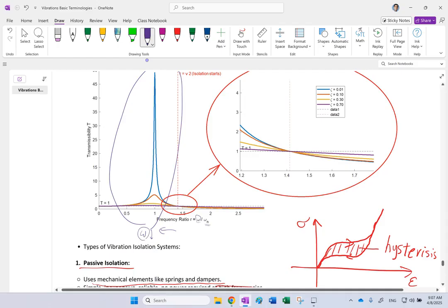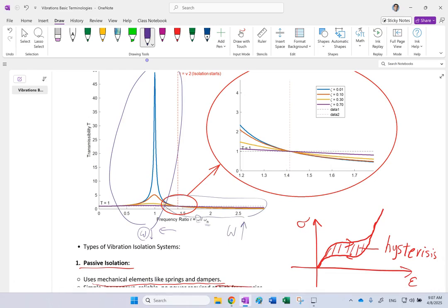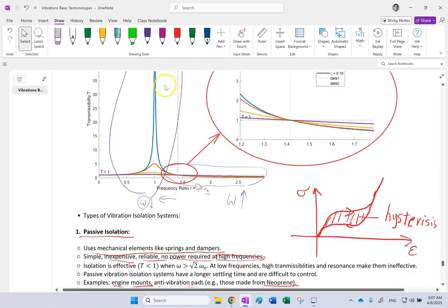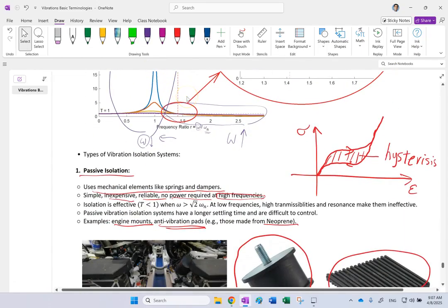So you might get some big bumps in the road, okay, and big vibrations up and down the ride, we call it. These passive isolators are really good in the high frequency range, and picking better C's and better K's will make this region better. But again, nothing is under your control. The good thing about them is they are inexpensive and they do not require any power.